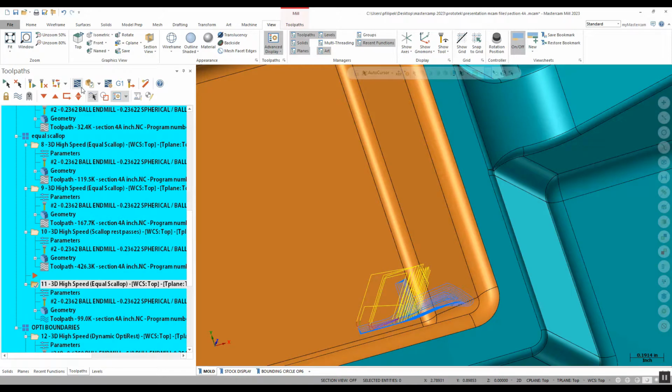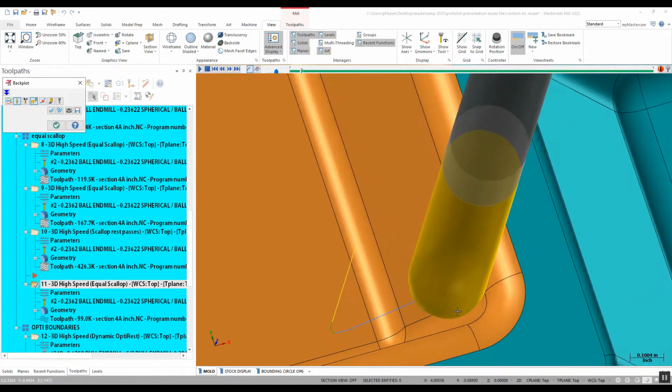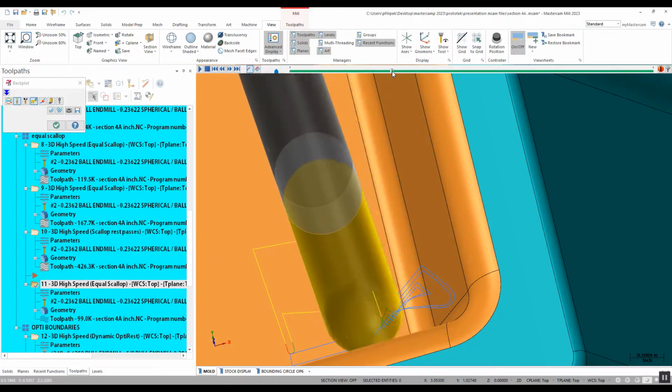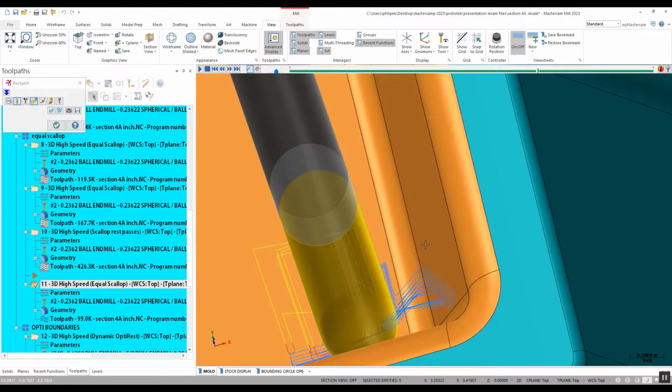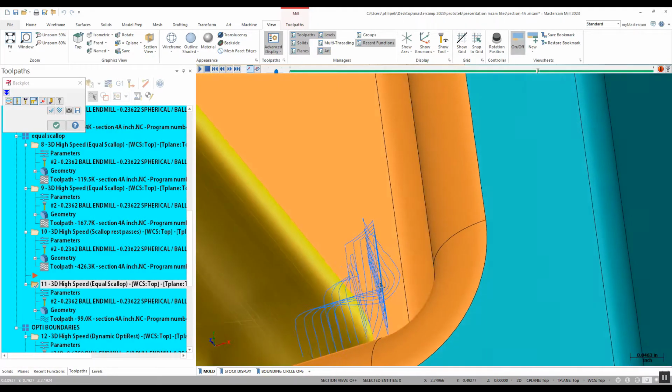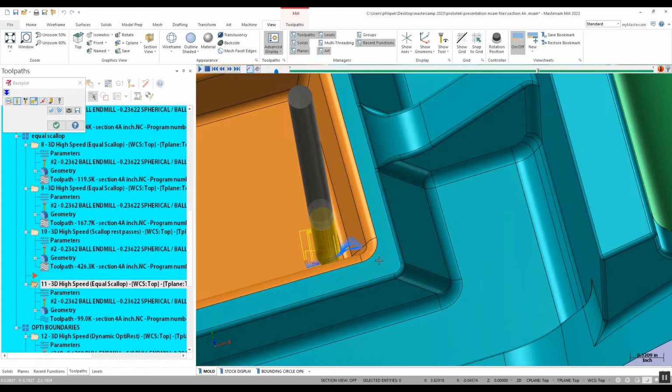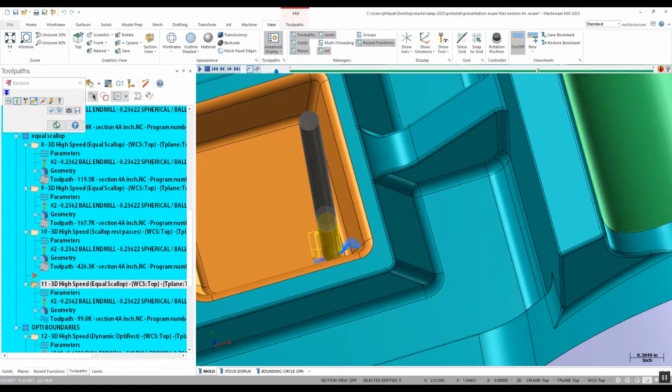So now if we look at this, what I'm getting is a cut away from the stock, and then the next cuts will work in that step-up value. So once this runs through, now I have really two cuts out here. See the range there? I got one cut out here, one cut in here. Now this is only for semi-roughing. So this is only going to really apply to semi-roughing, but this is going to give the ability to do step-ins where that material is left over, which can be really key to getting corners cleaned out in more complex parts or issues with corner radiuses. So definitely go back and try this.